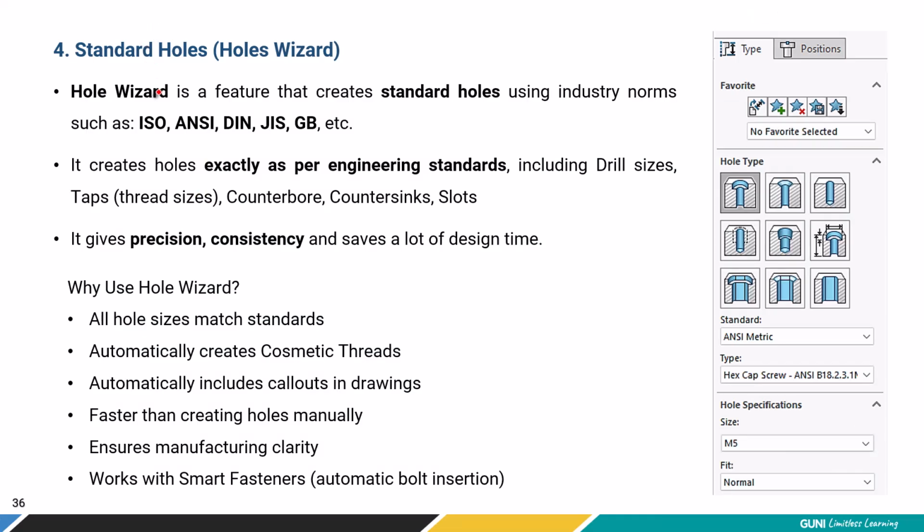Now let's explore the use of standard holes. Sometimes in SolidWorks this is referred to as the Hole Wizard. The Hole Wizard is a feature that creates standard holes. Now try to understand what that means. It has fixed sizes which are used in industries.